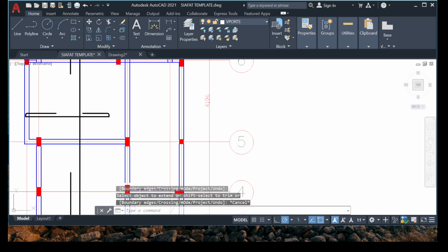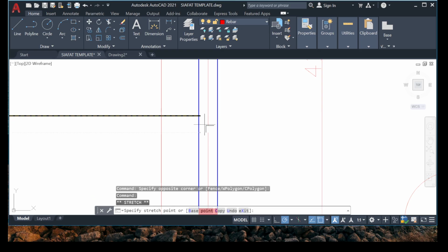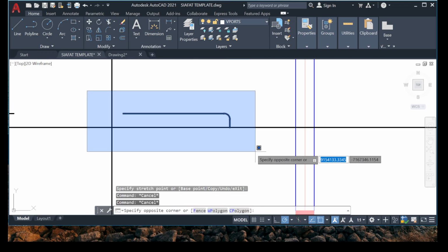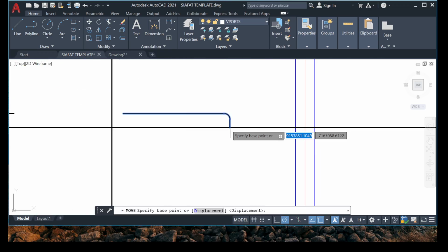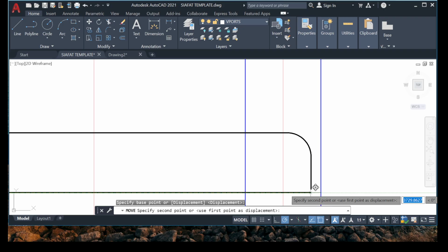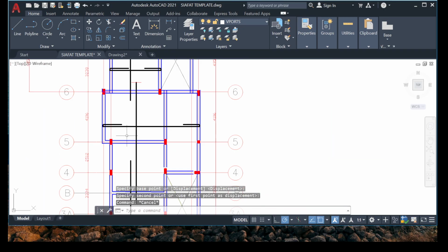That's what we have here. So let's see. Let's take this. Let's bring this here. Are we together? So remember, we are still working on the bottom reinforcement. Let's copy this. Let's bring it. Now remember that your concrete cover should be what? 25 mm. Now this is what we have for this.